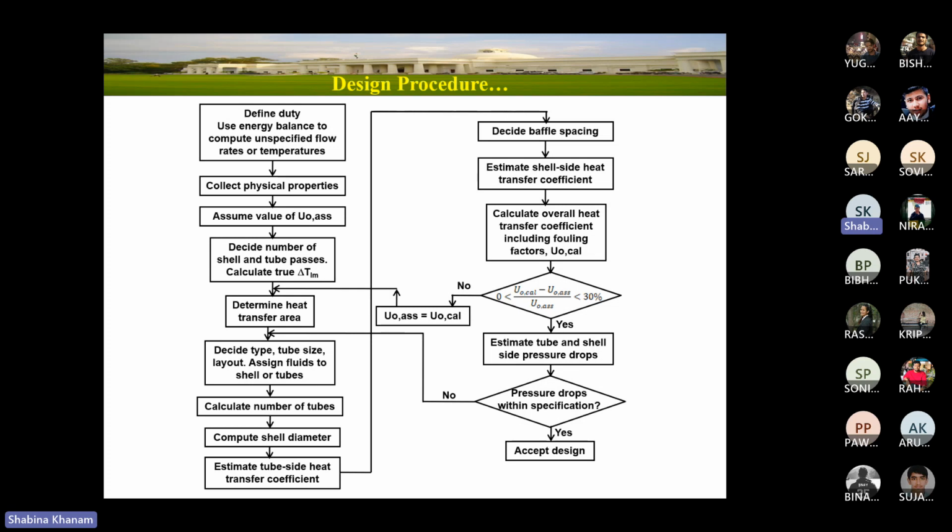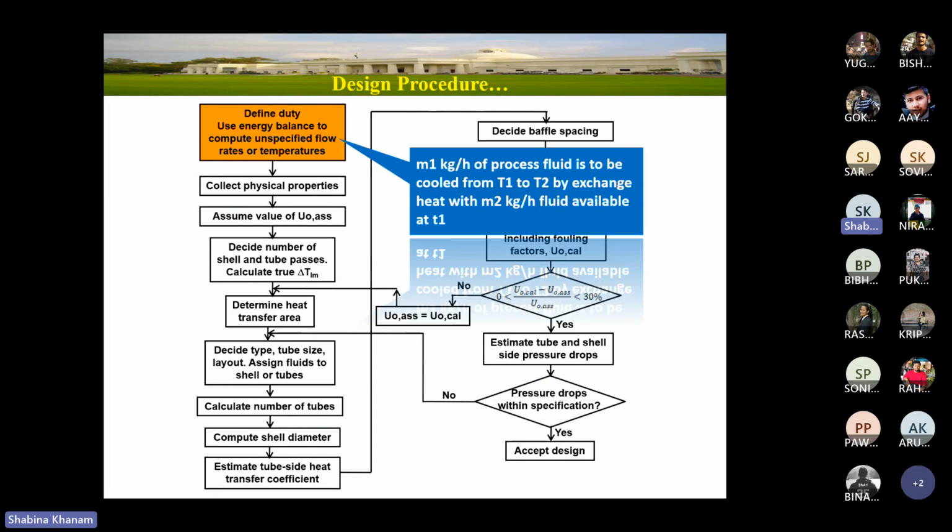Now in today's class I will discuss this design procedure in detail, discussing each and every step. So let's start with the first one, that is define duty: use energy balance to compute unspecified flow rates or temperatures. As we discussed in the last class also, when we consider the design of any shell and tube heat exchanger, or not only shell and tube, but double pipe and all,